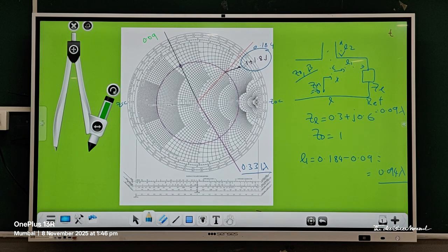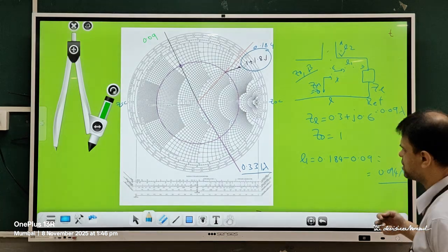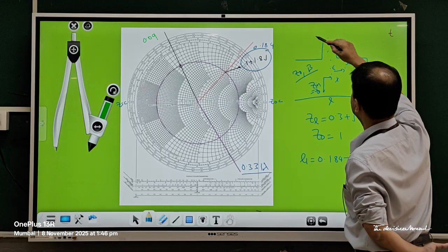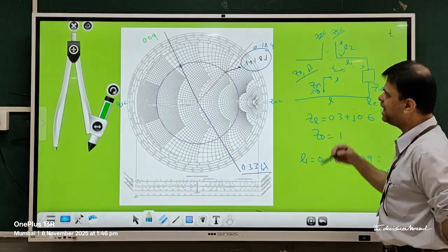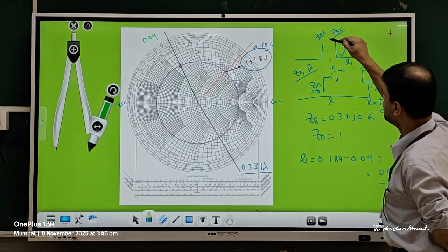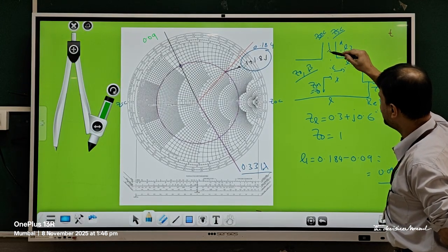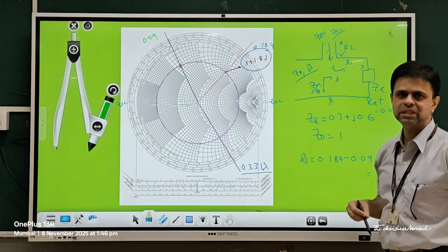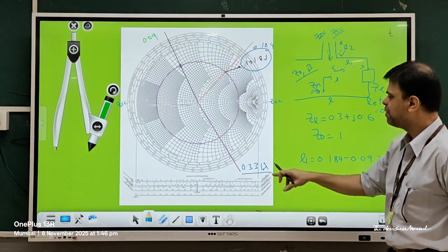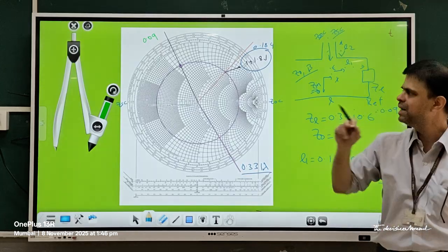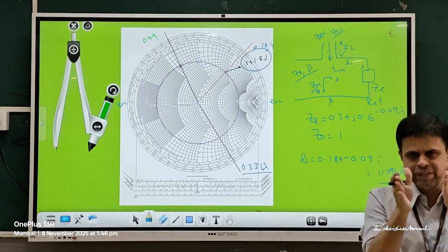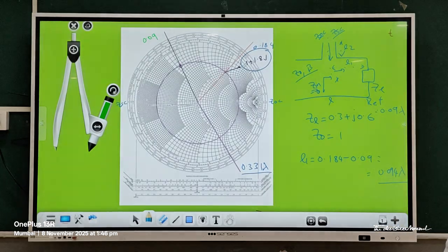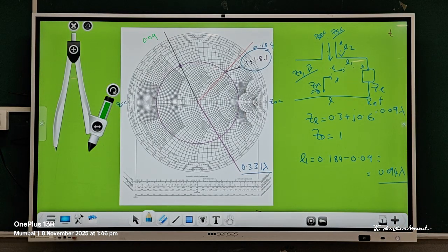Now you are going to realize the open circuit and short circuit series stub. So either it will be an open here, that is ZOC, or it will be a short here, that is ZSC. Because this is either a short circuit or an open circuit condition, you will move towards this point. In the process, you are required to realize the impedance of that open or short circuit line as minus 1.8j. So we are moving towards the generator.